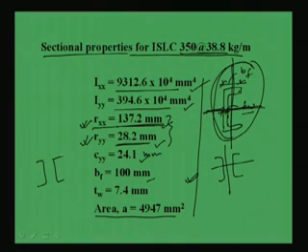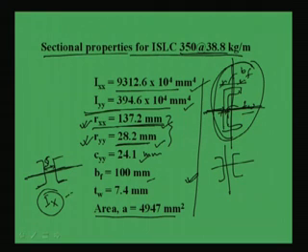So, if we can increase the radius of gyration by placing the sections in a proper way, we can increase the strength of the built up section. Up to what extent can we increase it? We know Ix is fixed, whatever placing we are doing, because the combined Ix is the summation of the two individual Ix. So, we have to increase the Iy up to Ix, because if we increase it further, failure will start from the Ix point of view, about the x axis.